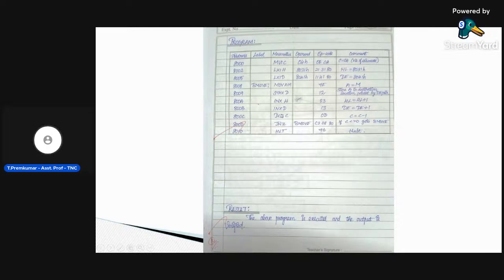The next process is we're going to check if C is not 0. So, jump not 0. The register we have is C. If the C register is not 0, then I can say B move. B move is nothing but what we refer to as a block move. So the address we are asking it to go to is the memory location 8008. Again it will come there, and take the incremented memory location and the data over there,